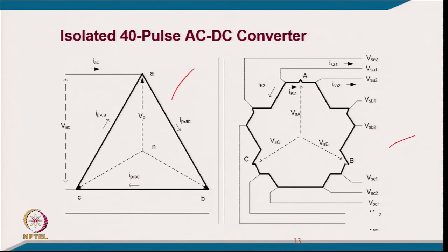That was for the non isolated case, where you have to use the connection corresponding to an auto connection, but here we have an isolation transformer. So, the primary is normal, and the secondary uses a kind of delta polygon connection to get a proper phase shift. You can consider here a set of three single phase transformers. These are the horizontal windings, where you are using several segments. In the first transformer secondary you have 1, 2, 3 and typically 4 segments in the horizontal one. Similarly, you can have the other 2 transformers.